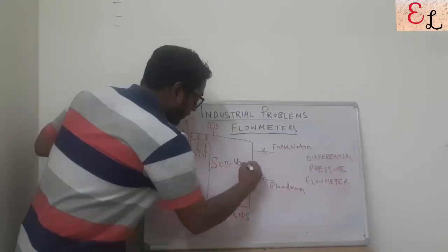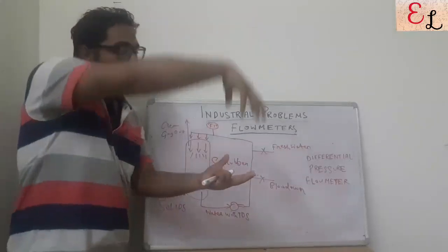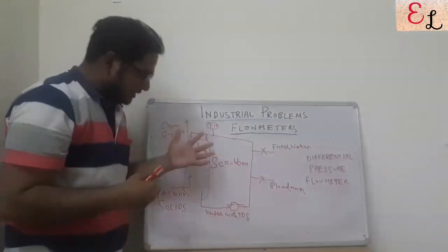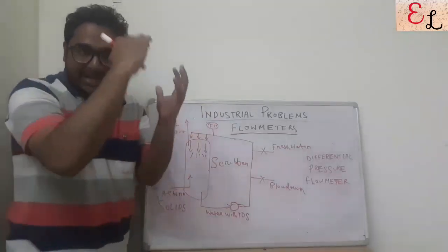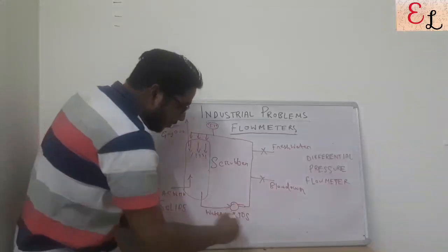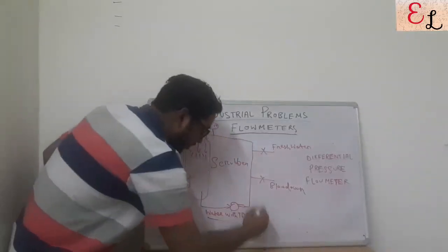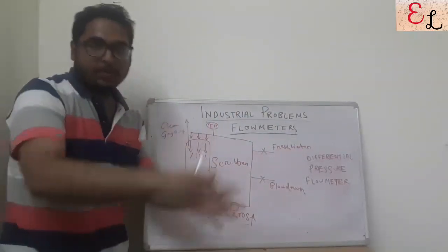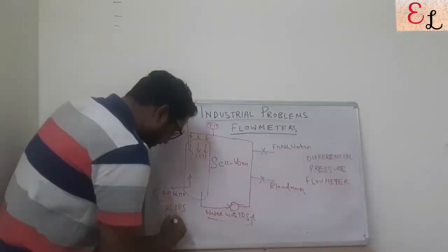And as you know, in a wet scrubbing mechanism, water is brought in contact with the incoming gas in a counter current way, and hence the dust that is present in the gas is removed by the incoming water. The water with a high amount of total dissolved solids, TDS, is coming out and being recirculated. There is a continuous process wherein the gas is coming with varied dust loads, that is, varied amounts of solids.